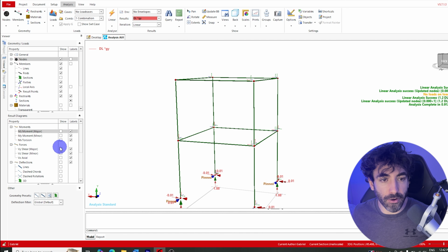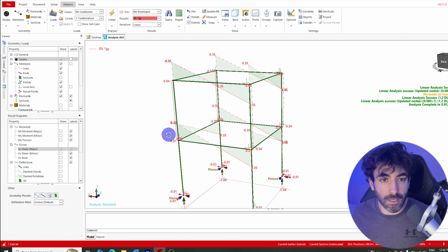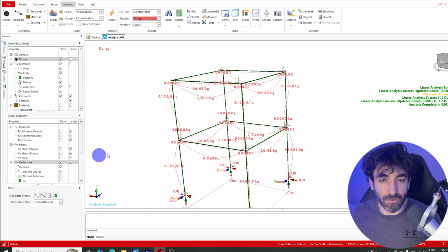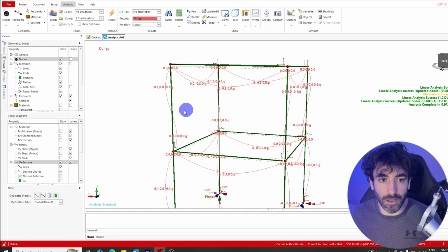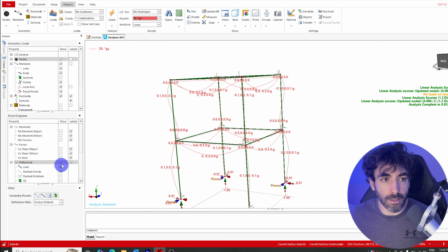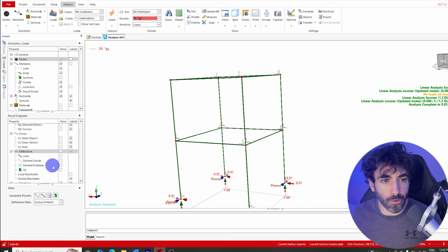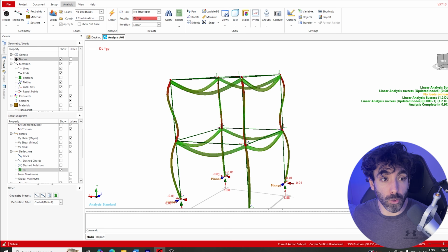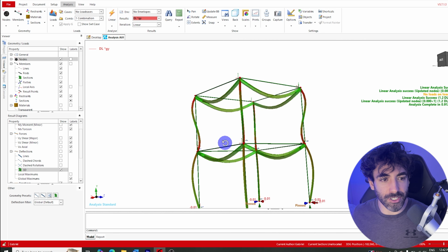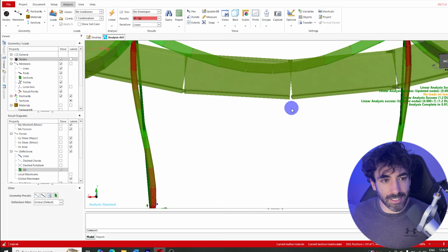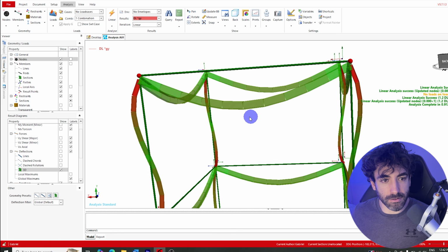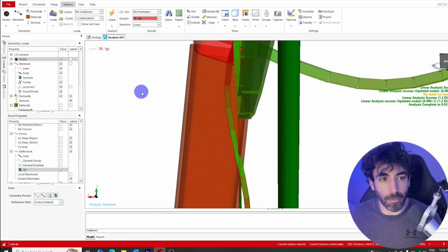Shear force diagram looks alright. Deflection also looks fine. It's only under self weight, so I wouldn't expect any large numbers. Let's see what this 3D button does. Well, that's pretty cool. You can tell which face of the element is in compression or tension, right? It looks like the bottom fibers of the beam are trying to open.